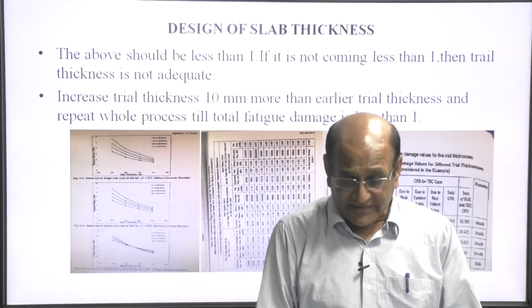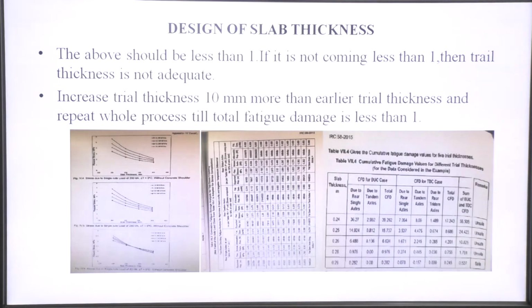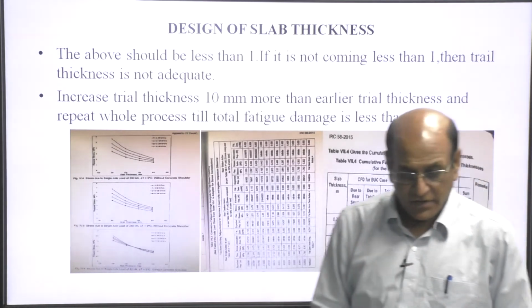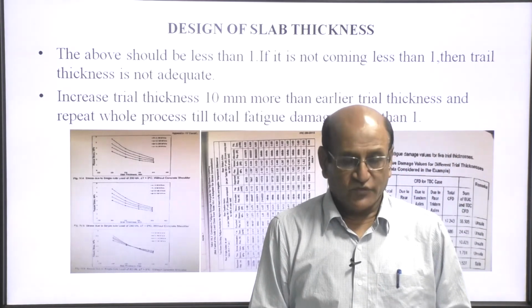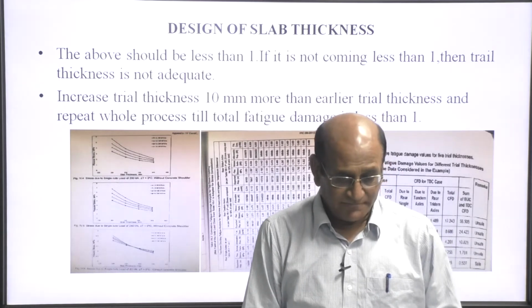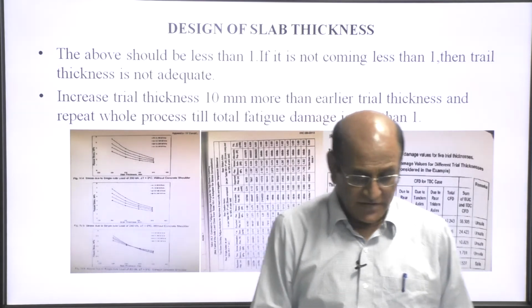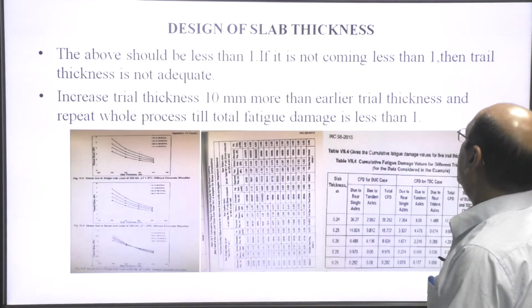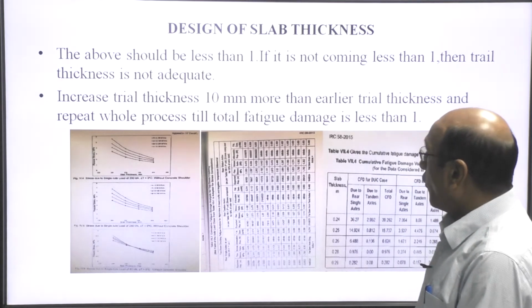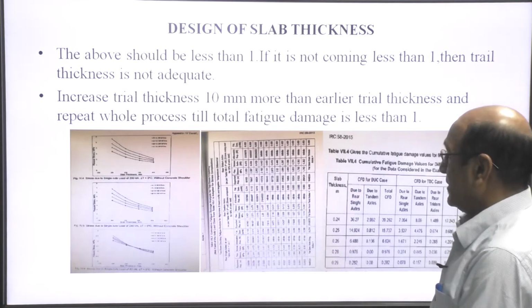If it is not coming less than 1, then the trial thickness is not adequate. Increase trial thickness 10 mm more than the earlier trial thickness and repeat the whole process till total fatigue damage is less than 1.